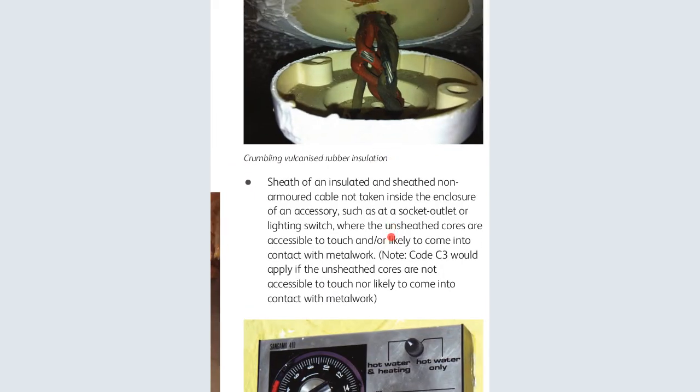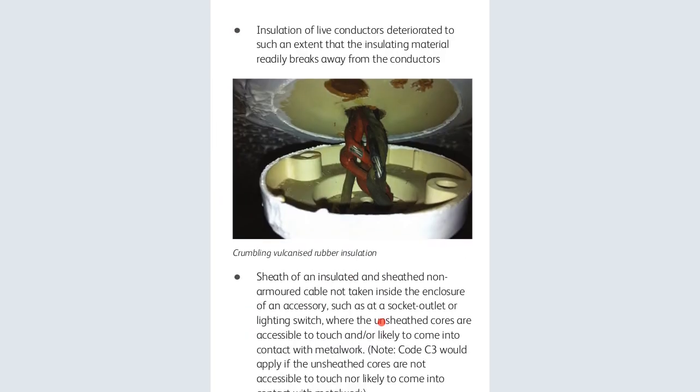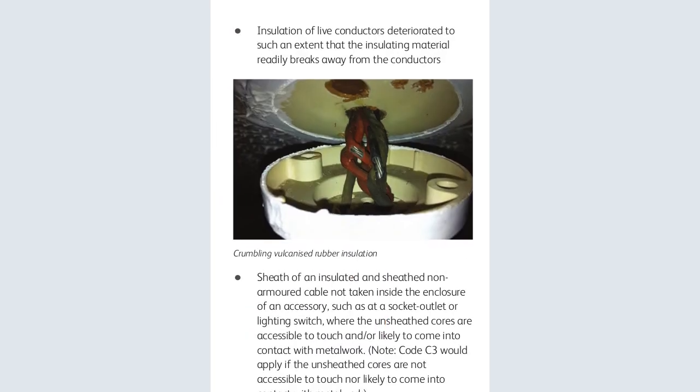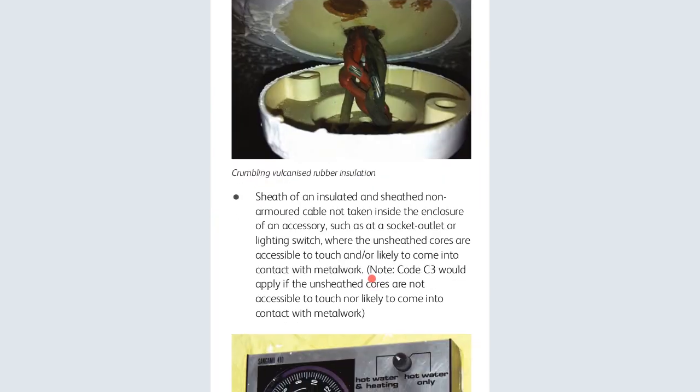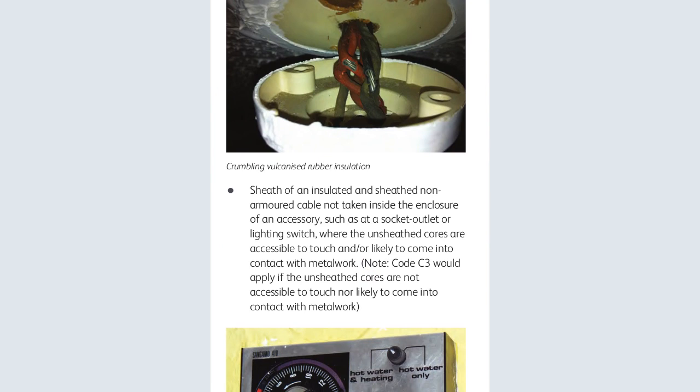Now look at this one. Maybe what happened here is that when the pulling of the cables was being done, there was a peeling of the insulation, and this can easily lead to a short circuit or even a fire. Because the moment the live and the neutral meet, there is always a short circuit. So we need to take a lot of care, and when inspecting, this has to be recorded.